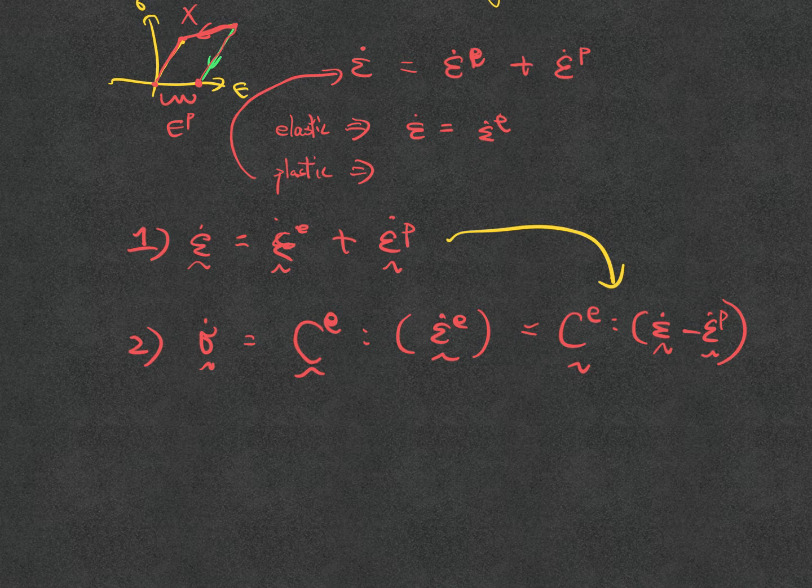We assume one more thing to make the model easier: that the material has a linear elastic behavior. How do I know it's linear? If I have something non-linear, I cannot describe it with just linear operations. I have to add a quadratic term if it's a polynomial, or CE itself probably depends on the strain or whatever. But CE here is a constant, so even though it's a tensor, it's still a constant, so we know that this is a linear relationship.